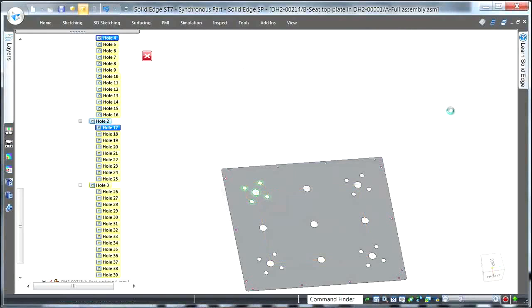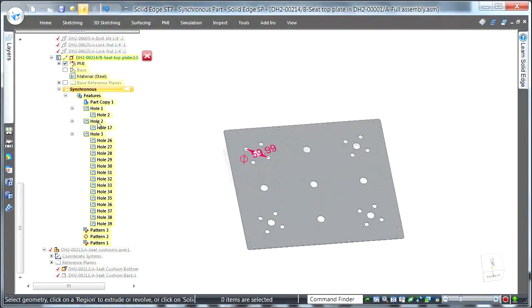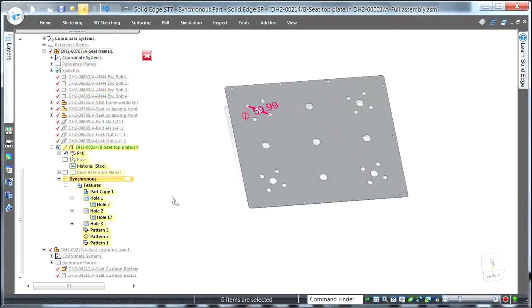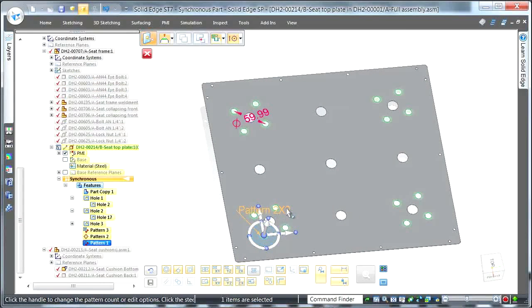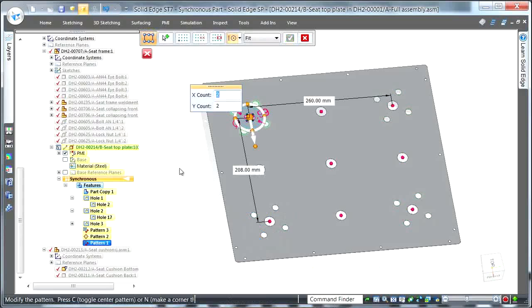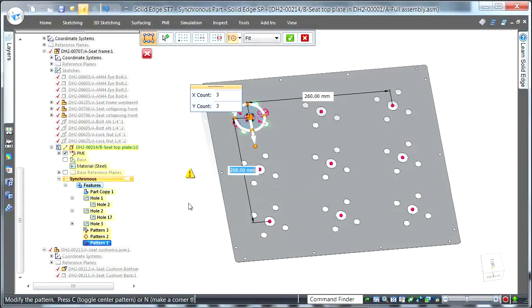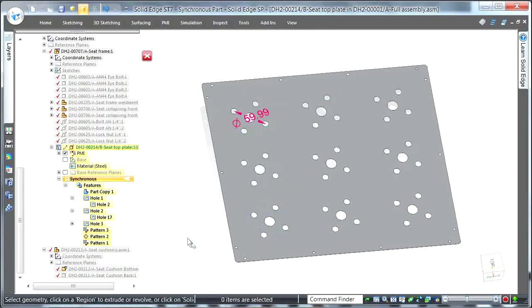So we'll adjust that. But if then post that edit, we wanted to adjust one of those individual patterns, we could do that also. So if we change that circular recognition from 4 to 6, that will then update all of those patterns of patterns. So great flexibility when you're working with imported parts. Yep, looking good. Back to you, Dan.